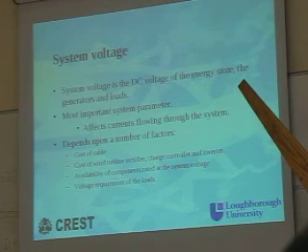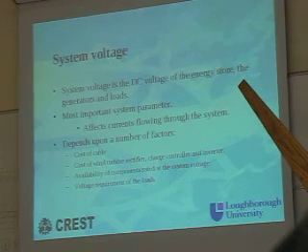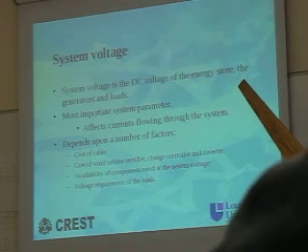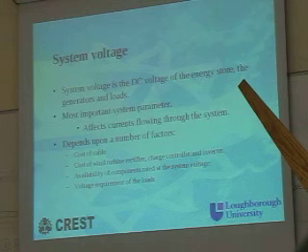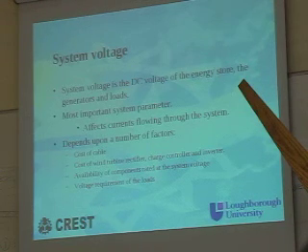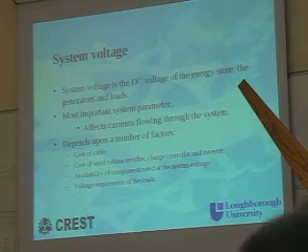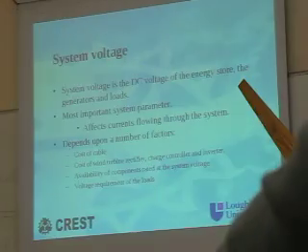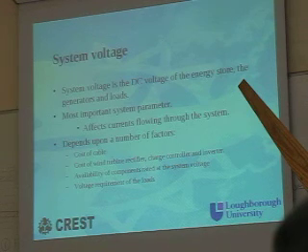It affects, as I was talking before, 100 amps. So if we had a low voltage system, we had 100 amps flowing. If we had a higher voltage, we have a much lower current, and we know that power or resistive losses are related to current squared. So doubling our voltage will halve our current, which will reduce our power losses by a factor of 4. So actually, it's even better to increase our voltage.